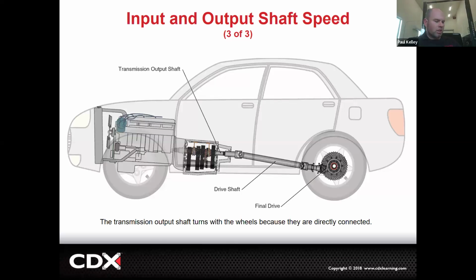What it'll do is save you from having to completely disengage the clutch and completely re-engage the clutch. So you can actually put it in a no lift shift mode where all you've got to do is just tap the clutch pedal. Right. So you'd be wide open throttle, gas, and then you just tap the pedal and do a really fast beep, beep. They do that from factory, believe it or not. But if they don't, they also sell a thing. They'll call it a no lift shift box, or they have different terms.